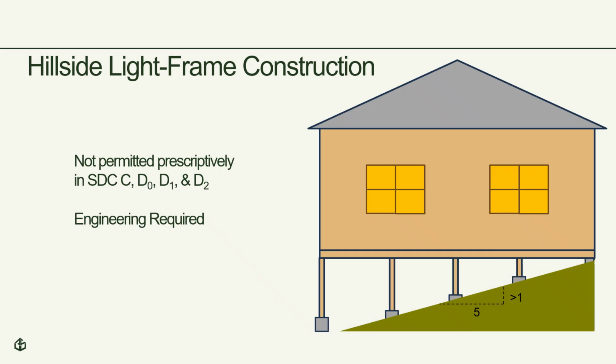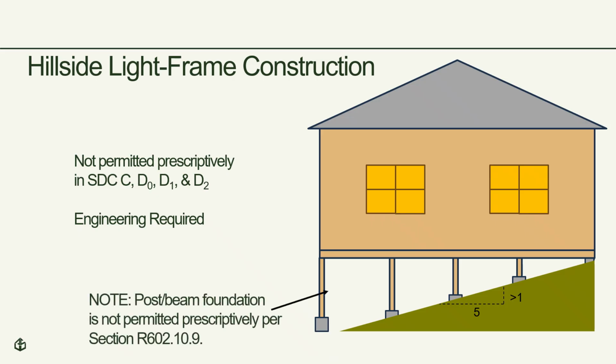Something I want to point out about this particular provision is that while it discusses post and beam foundations and these limitations regarding slopes and heights of those posts and beams, it's important to understand that per section R602.10.9 of the IRC, post and beam foundations that support brace wall panels are always required to be engineered.